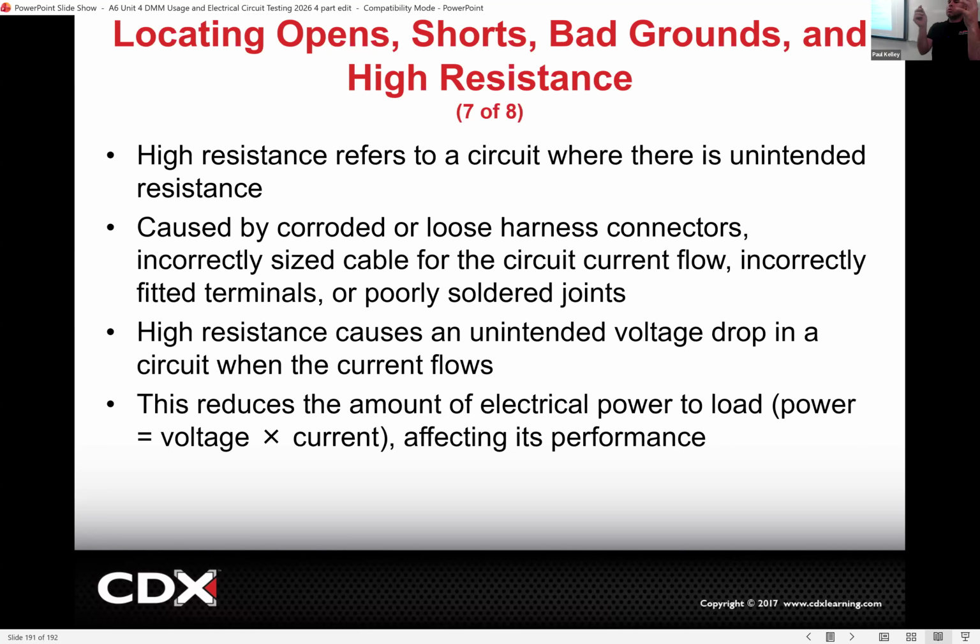On the front side, truthfully, there's nothing wrong with front probing if you just lightly touch it. But who's going to hold it there? You've got to be in two places at once. So normally techs are like, send it. See, it'll hold itself as long as I ram it in there. Whereas with the back probe, it typically has the plastic part of the connector. You can prop it up against the connector, just barely make a connection, less harmful.